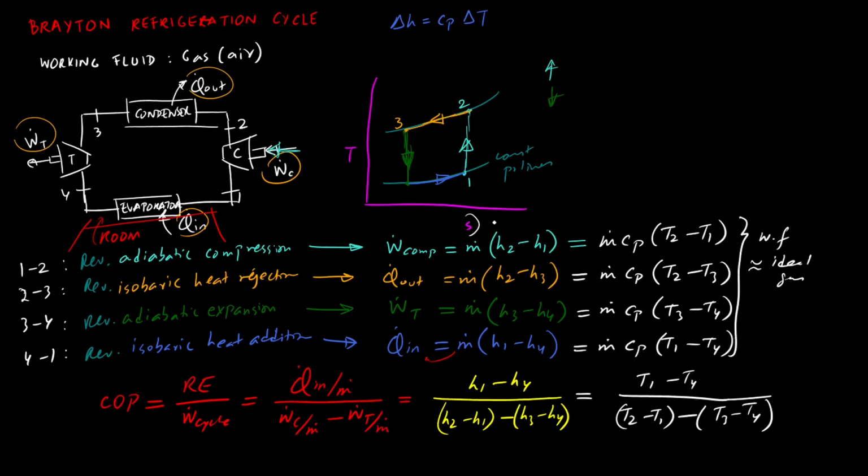So we've got entropy on the x-axis, and that means that usually with every process, entropy would have to increase, especially the ones where we've talked about the isentropic processes, which is process 1 to 2 and 3 to 4. So in these processes, right now, they're reversible. By introducing irreversibilities, they're both going to be non-isentropic compression and expansion processes. That means these would have to change.